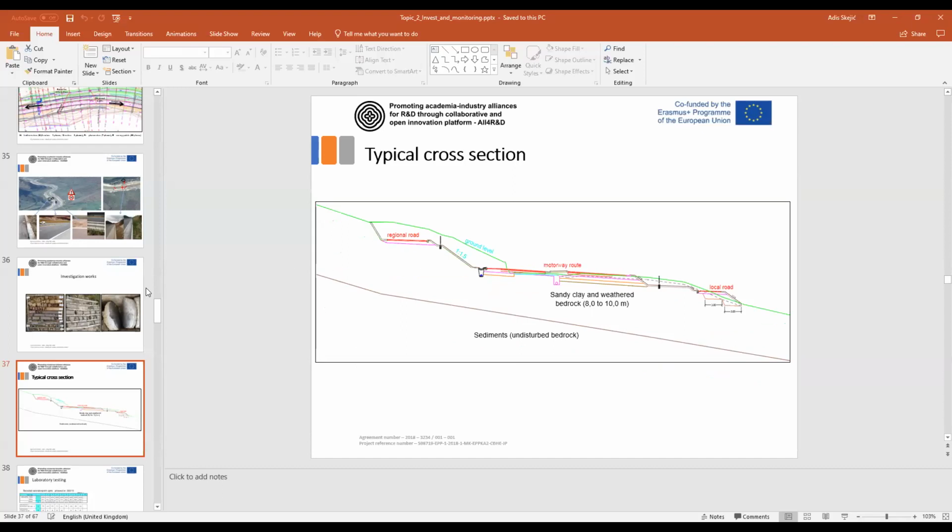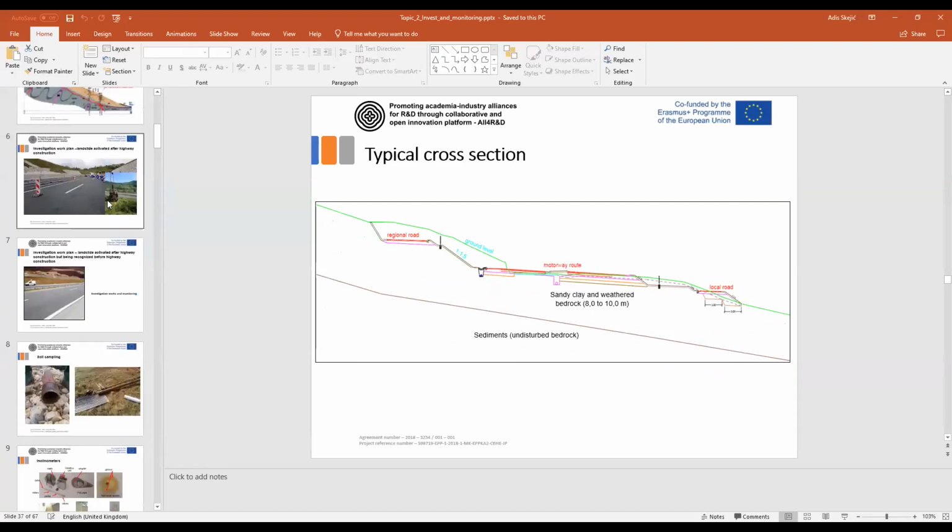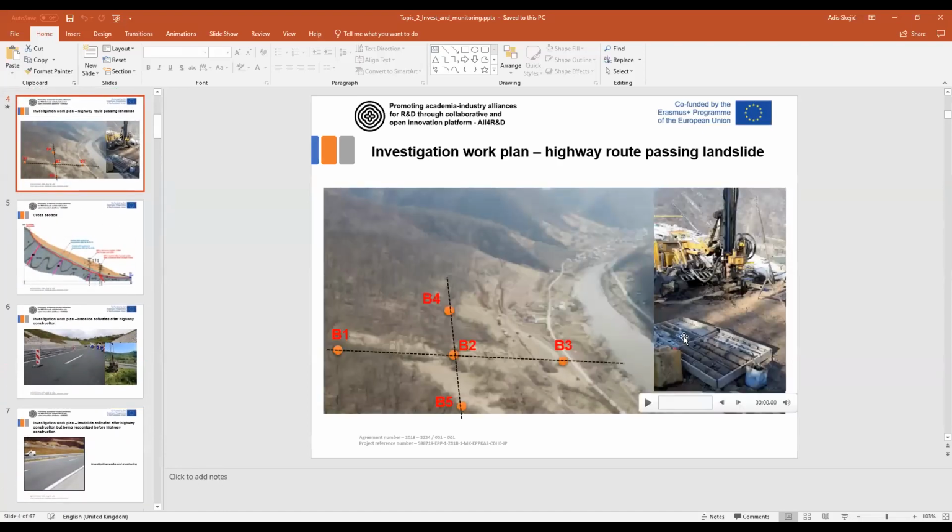You can recognize it as very good quality rock material, like it's here. You can see this very good quality intact material, not prone to sliding. So that's the main criterion in landslides: pass all the potential landslide area and enter the solid, stiff material, not prone to sliding.